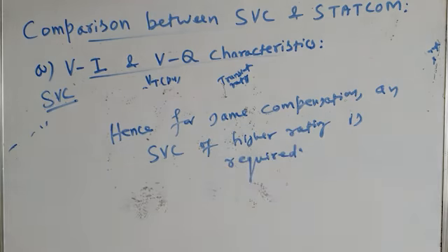These characteristics prove that STATCOM provides more effective compensation than SVC, because STATCOM maintains the current constant, independent of the bus voltage, whereas the current decreases linearly with bus voltage in case of SVC. So from these graphs, we have seen that STATCOM provides better compensation than SVC. This is the first point of comparison, and it goes in favor of STATCOM.